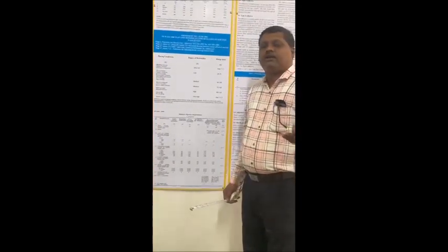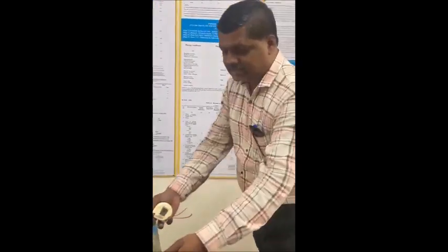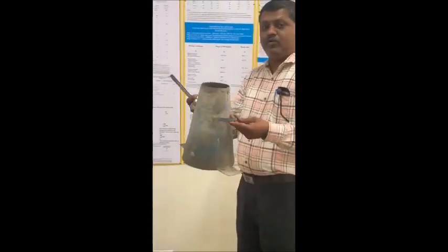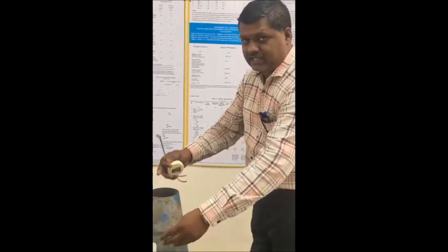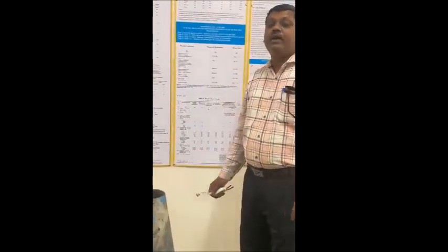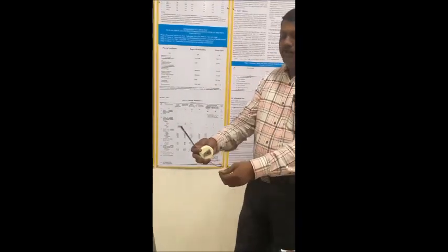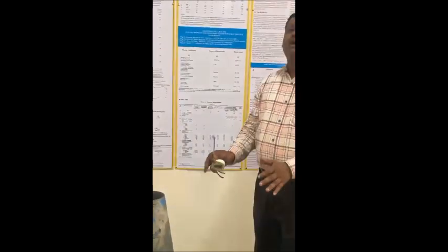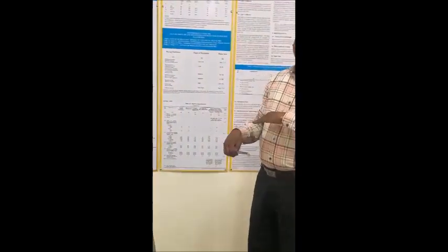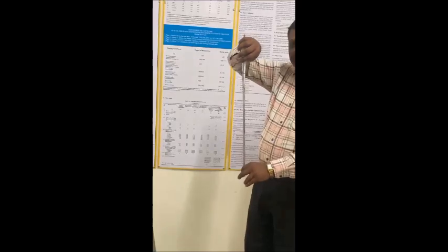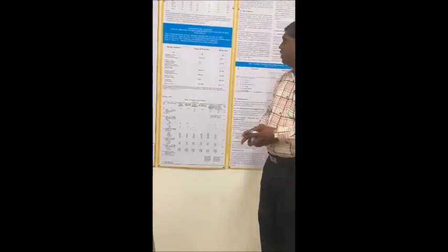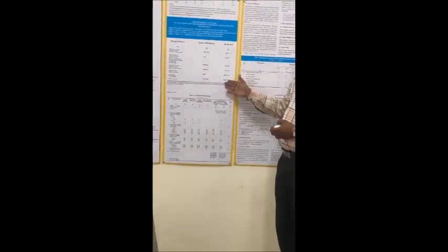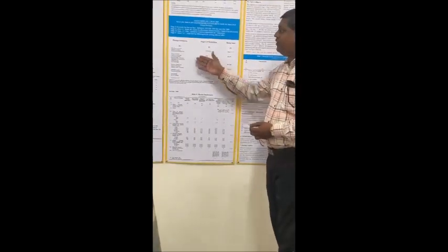Now the entire thing is based on the slump value. The slump test is the primary test of workability which is generally conducted on sites. You can see here this is the slump cone, and in the earlier video also I explained the slump cone test. Concrete is filled in this cone in 4 layers and tamped with 25 strokes so that compaction occurs. Whenever this cone is lifted vertically, the unsupported concrete subsides, and the subsidence from the height of the cone is measured with a tape. That is called the slump.